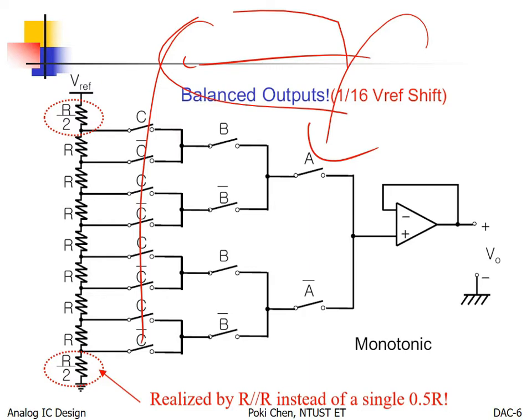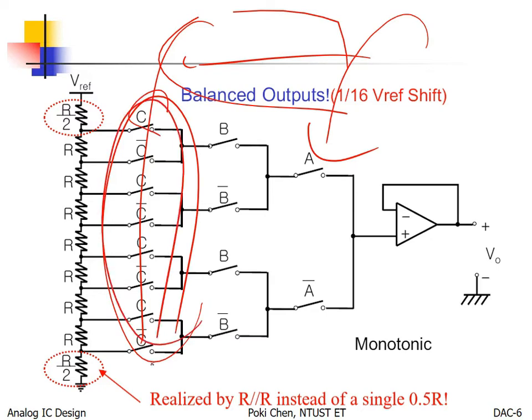Sorry for that, especially for LSB. Wow, it needs to turn on or off so many switches, right? It doesn't make any sense. The input bit may not have the good enough driving capability to do all of this. So you still need buffers.